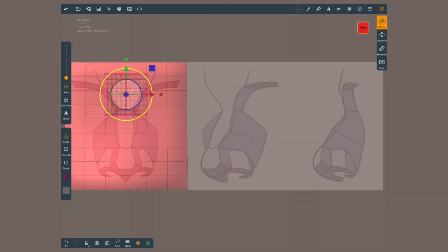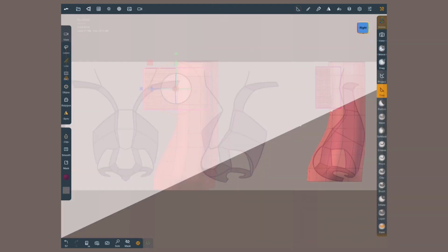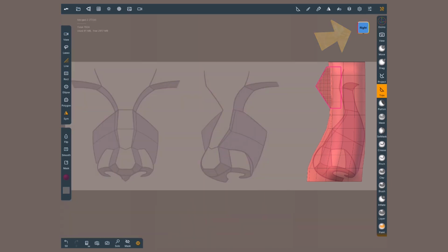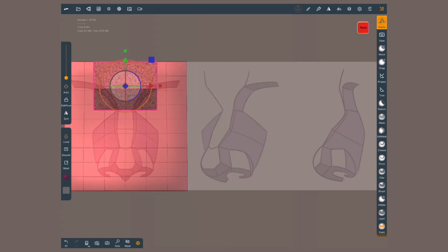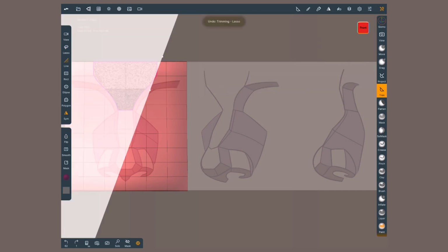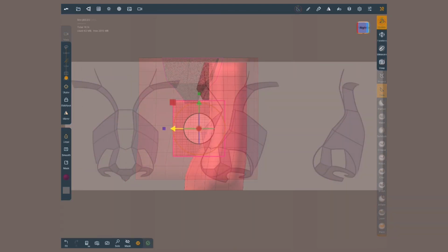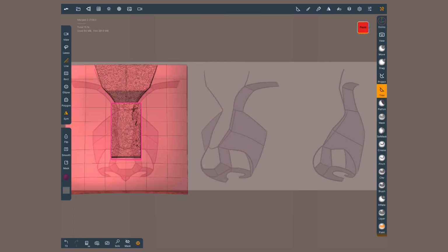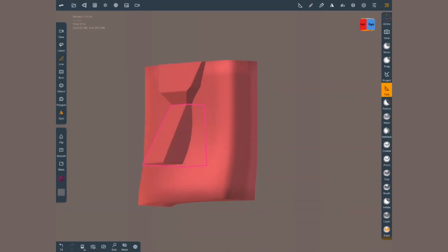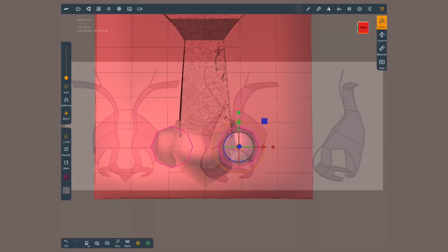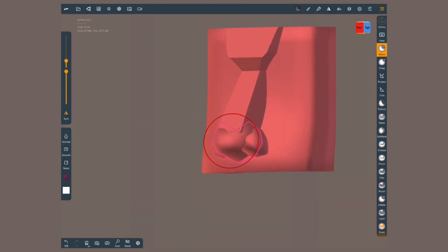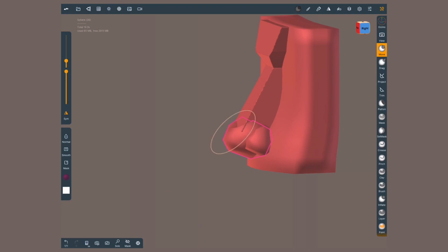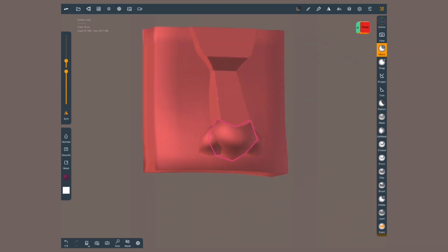Now I'll make a new cube for the glabella. Using the Snap Cube and my camera in orthographic view, I'll go to a perfect front and side view and make cuts with the Trim tool to shape it as a funnel. For the whole bridge, I'll make a new cube and trim it from the front and side. For the ball and wings, I'll make spheres with very low resolution and shape them with the Move tool and Gizmo. Above everything, prioritize having front, sides and bottom planes.